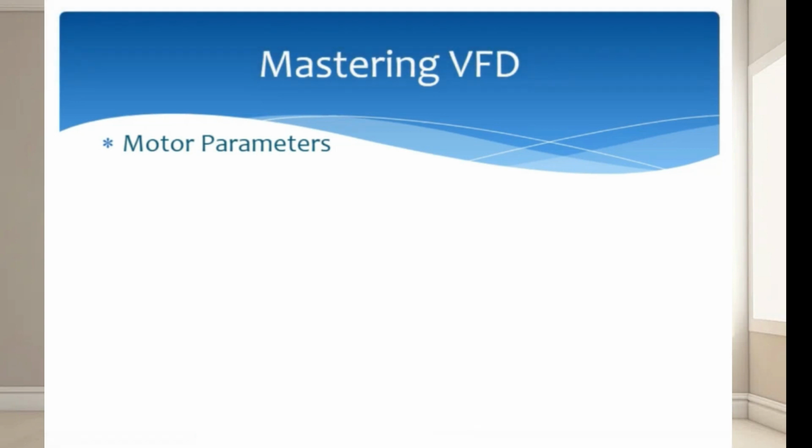Before we program anything, the primary subject is to deal with motor parameters first. Moving on, we need to program rated voltage, if it's either 220 or 380 or 400 volt. It could be any value, but we need to know and we need to program it. We also need to know the frequency of motor. Typically, it is 50 or 60, but sometimes it could be a different value.